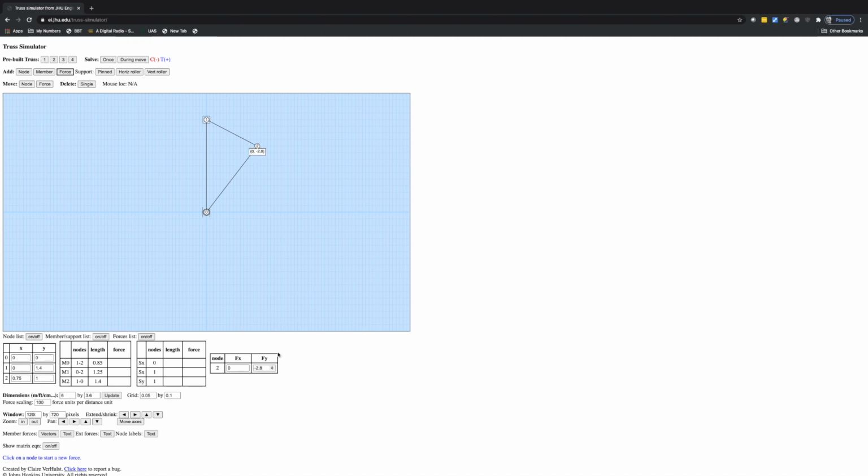When you do that, it makes this really short because there's a force scaling that scales the forces according to this grid. If I make this a 1, it wouldn't scale it at all, and I get a pretty long line. If I count that, this starts at 1 and ends at minus 1.8, so the total length is 2.8, which is what we're expecting, and the minus sign means it's pointing down.